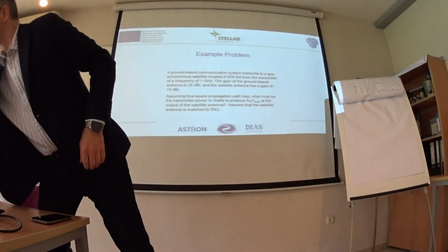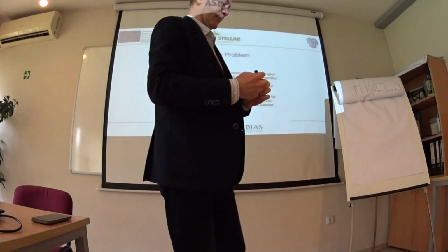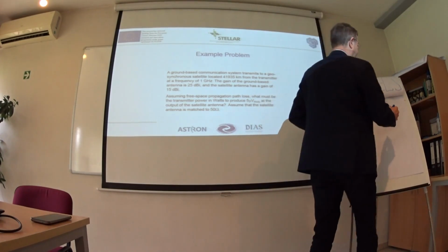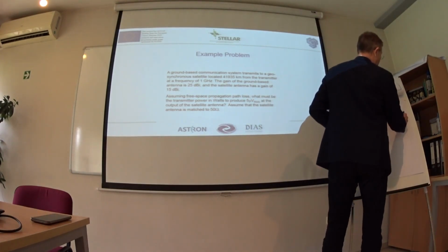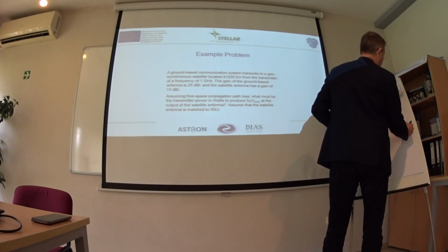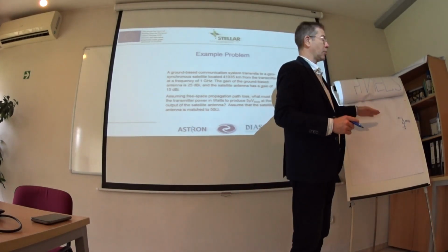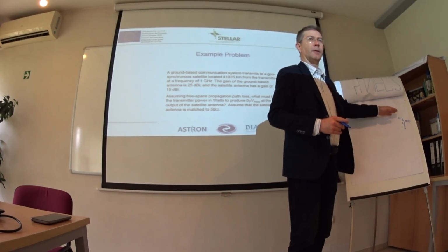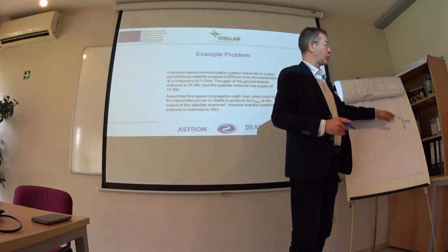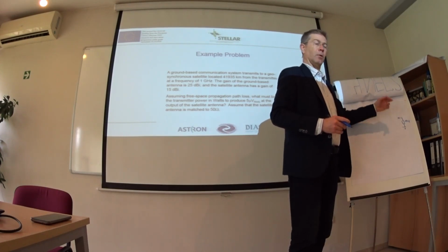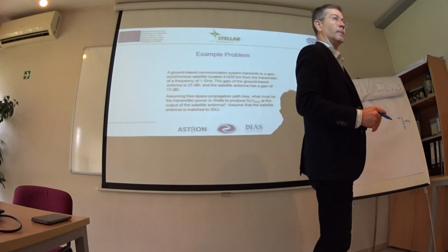First of all, you have a 50 ohm matched load. What does matched load mean? It means the whole transmission or receive path is matched to that 50 ohm. So we will have no reflection loss from the load. This is the input impedance of the receiver.